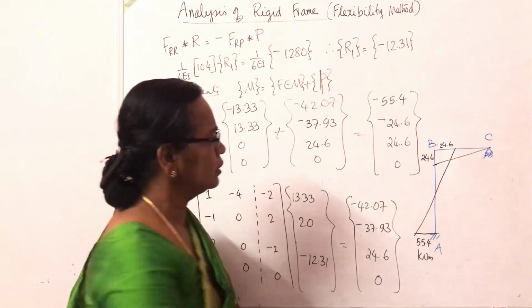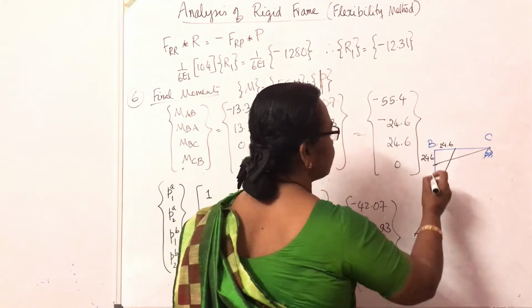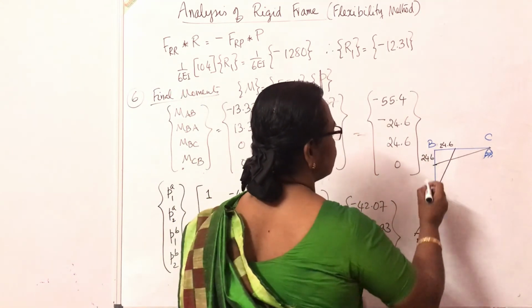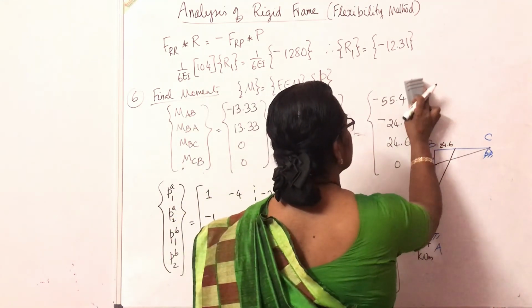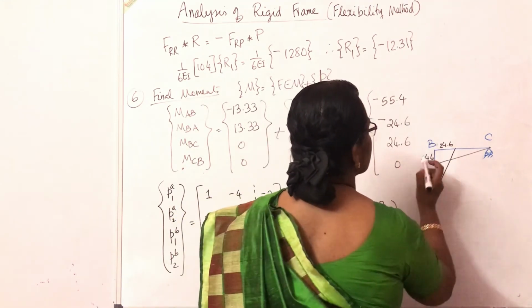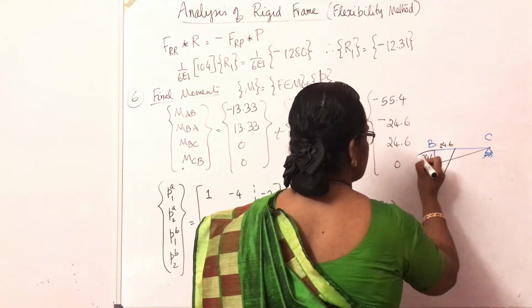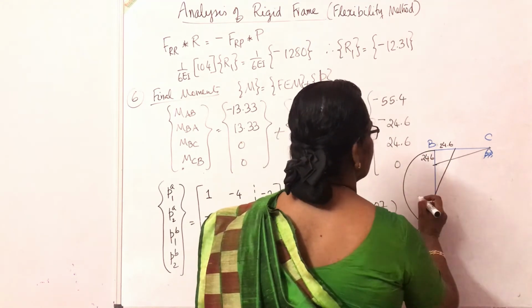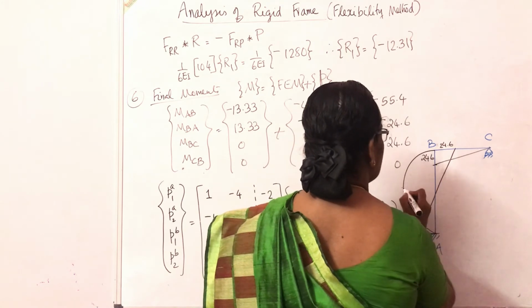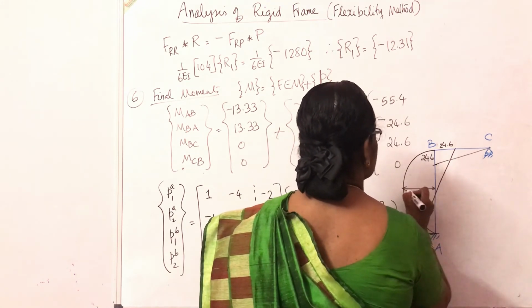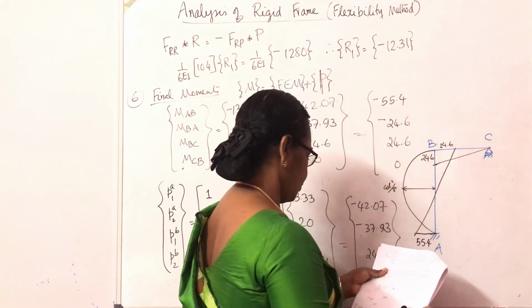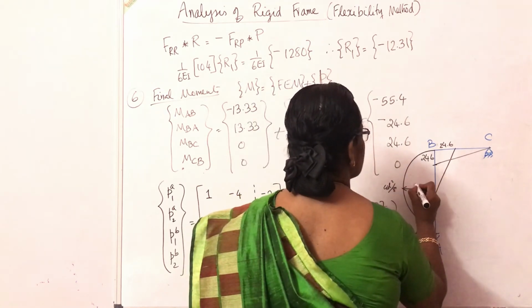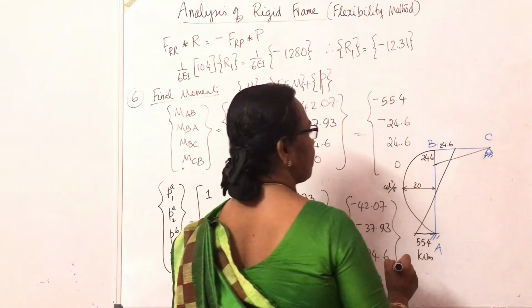So we have drawn the fixed end moment values, or the internal moment values at the support moments. Now in this element there was UDL. So you have to superimpose. You have to draw the free bending moment diagram. And this value at the center is going to be W L square by 8. It works out to 20. This is 20 kilonewton meter.